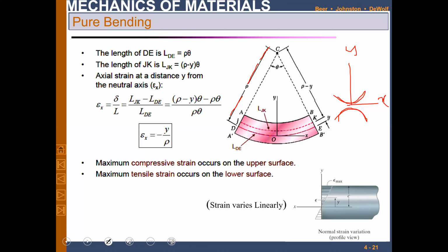This is the neutral axis we have, and then this is basically the y. Any other axis, these are dotted axes, and the maximum is obviously this distance C, where bending will be maximum. That bending may be compressive stresses or tensile stresses. In this part it will be compressive, in this part it will be tensile, right?